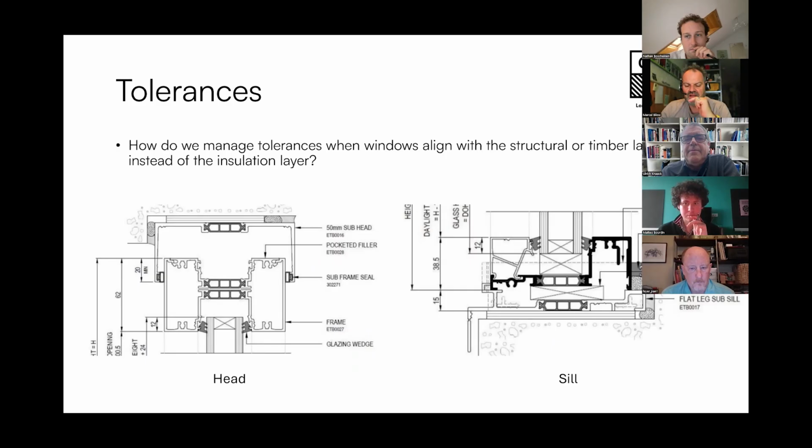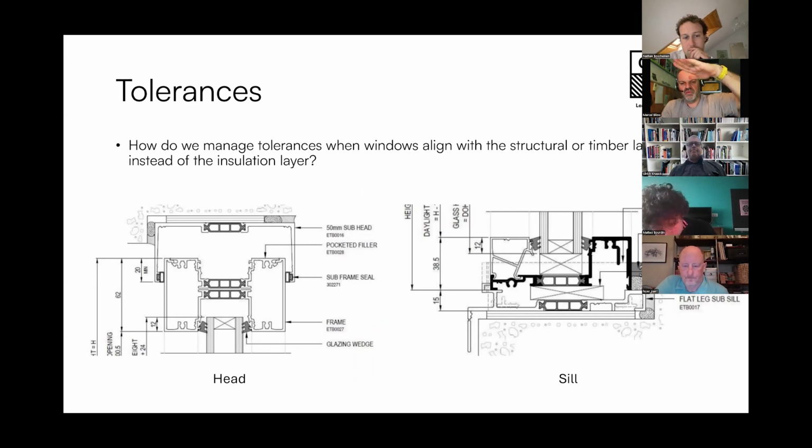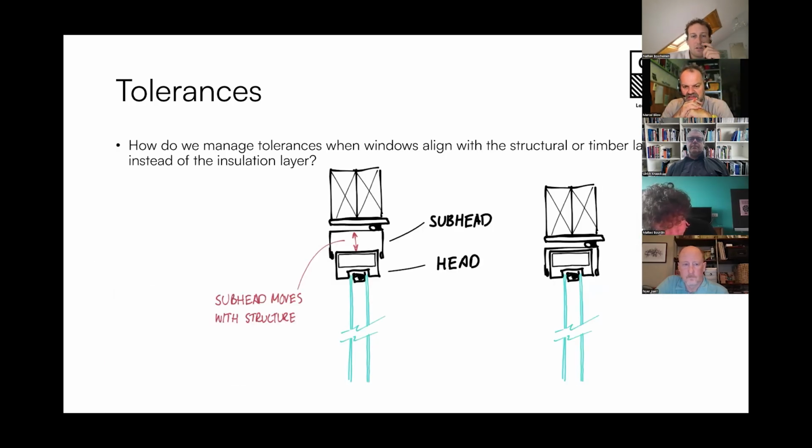That is the profile that will allow us to work with movements of the facade. Think about a large span opening of 6 meters or whatsoever, and the structural engineer tells us that there is a movement of the ceiling or of the beam possible. Then you have to make sure that you use a profile like that. Maybe you can go one slide earlier, it makes it a little bit more clear in general.